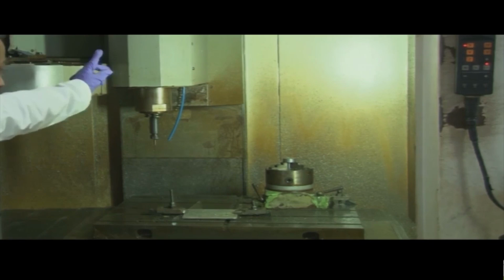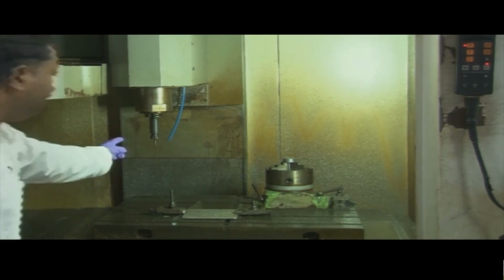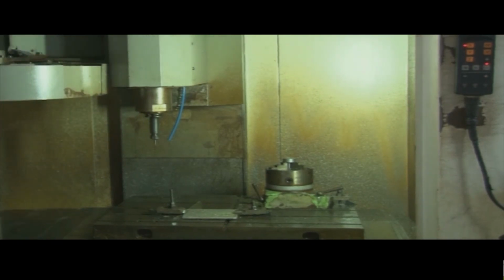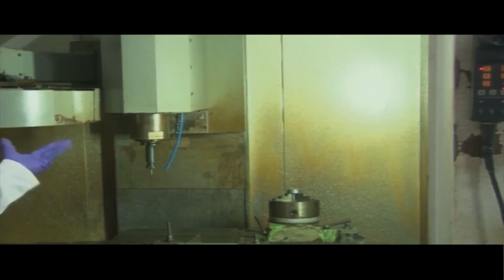So, in Z axis we have the spindle. The spindle provides rotation to the tool, and the tool is held in the spindle with the help of a tool holder. We have different kinds of tool holders, like chucks and collets, so many systems are there. This is held with a pneumatic system. These tool holders use a pneumatic force. The pneumatic system I will also show you at the end of the demonstration.